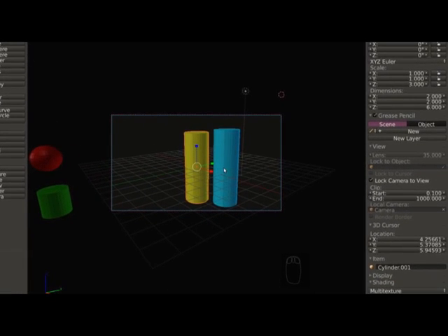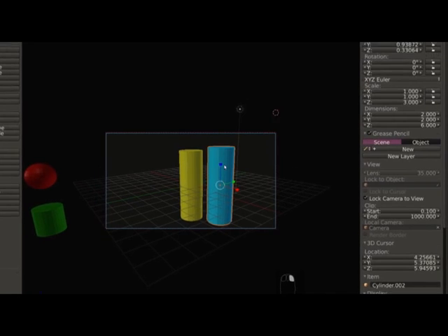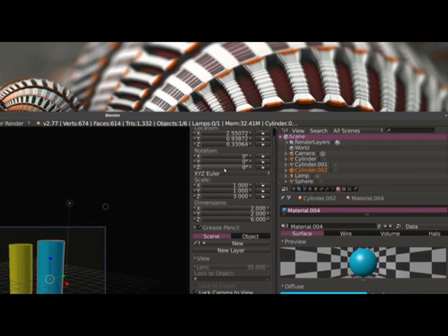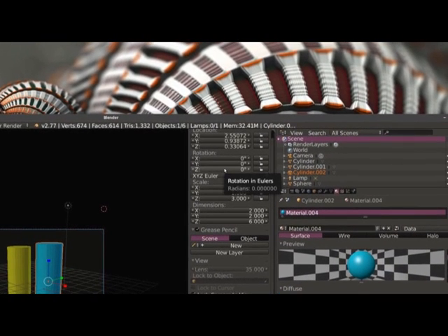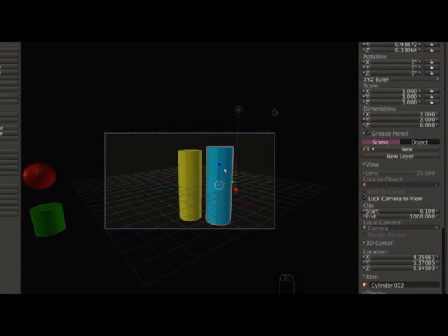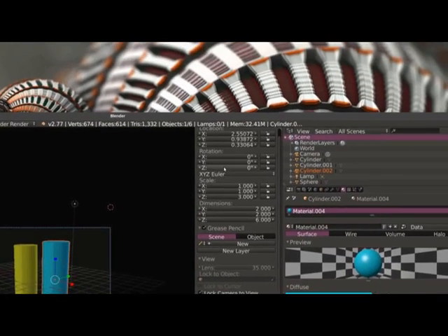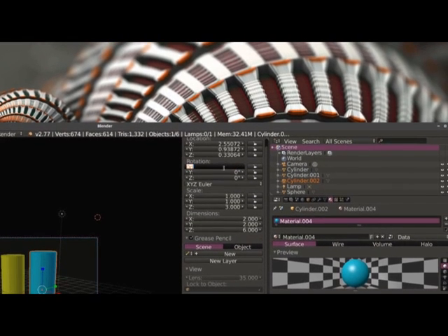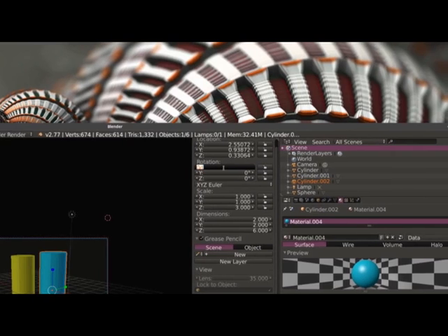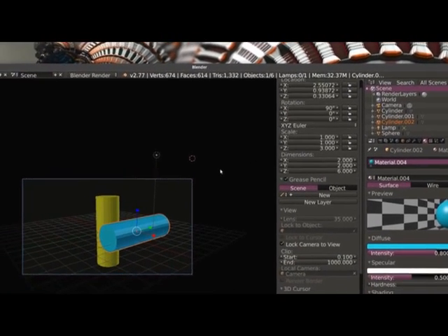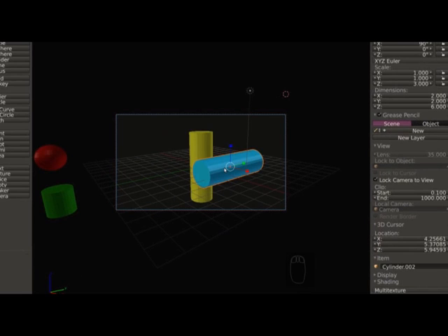You can see what happened over here is that moved my cylinder to the center of the universe, of our pretend universe here. Now, let's right-click on the blue or cyan cylinder, and let's go over here and rotate it 90 degrees. So I'd like to rotate it about one of the axes. As far as which axes, it doesn't really matter for this purpose. So let's do an x-axis rotation of 90 degrees. So I click under rotation, click on x-axis, delete what is there, and type 90 degrees. There's 90 degrees. So what does that do? That rotated my cylinder 90 degrees.